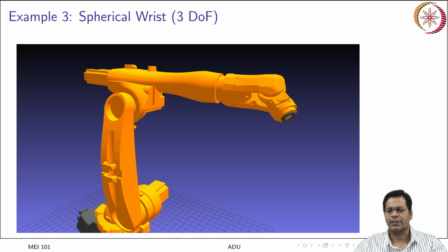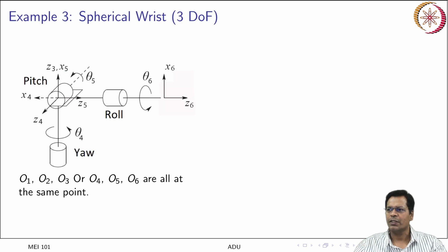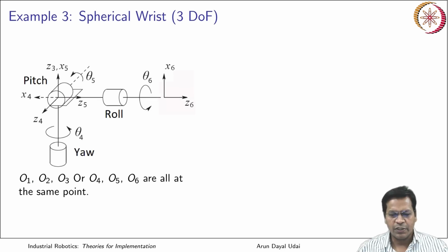So this is your axis 6. If you protrude that axis backward, it also intersects at the same location. So hope you got it. Let me switch it off and let us come to the kinematic picture of that. Here it is. The first frame that is visible here is part of the last frame of most 3 degree of freedom positioning robots.